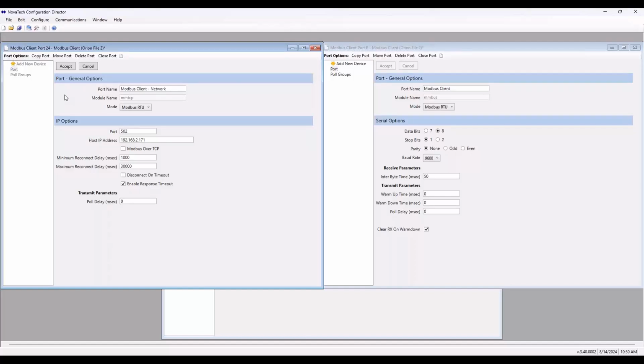Now, when can that become problematic? That could become problematic in the case, let's say you have an application where you're doing a Modbus communication, but you're going through a conversion, maybe like a serial to a network or TCP conversion. As you can imagine, that serial message is sent with a checksum within that message.